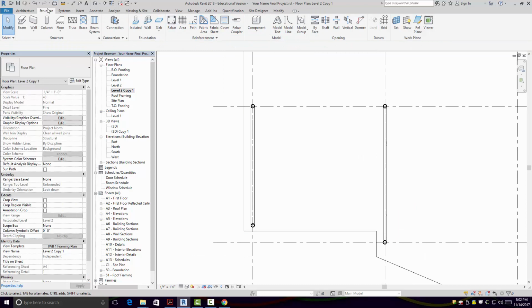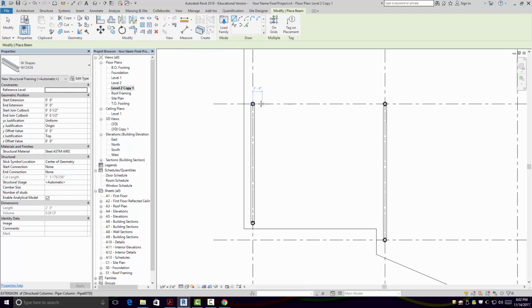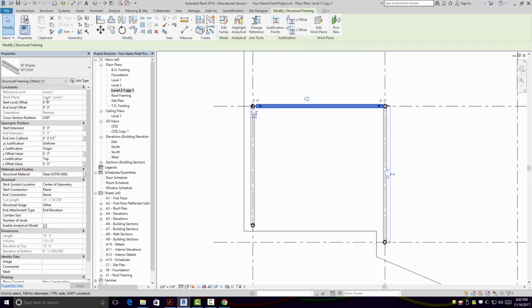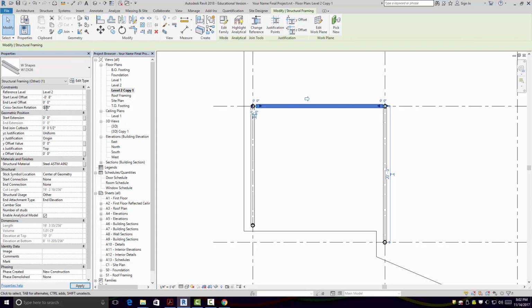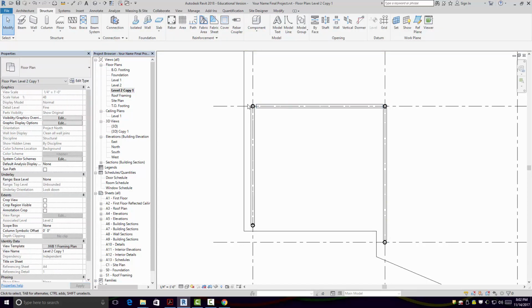We got a class of structural engineers now. All right, let me pick the smaller one and we'll do this one. In between your columns, you'll have beams. That'll be -8, because it has to drop below the slab, and it has to provide spacing for the joist, which hopefully I'll be able to show you in a second. 8 inches. You have to do both ends, so you could have a sloping beam.